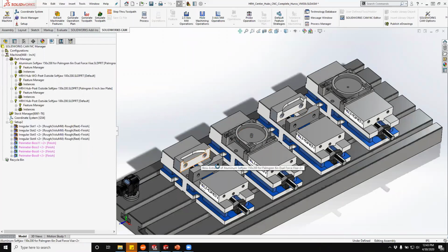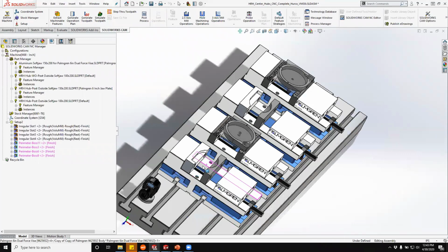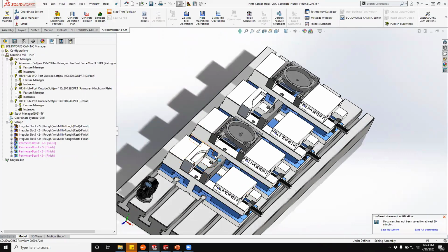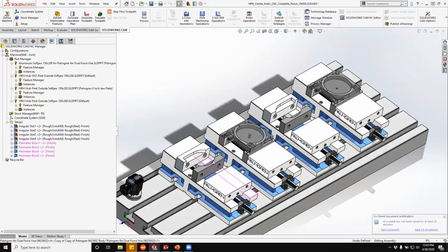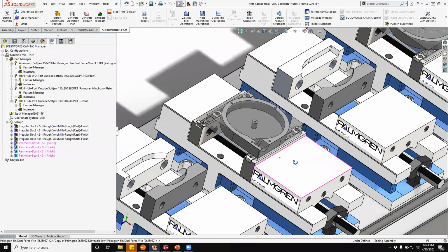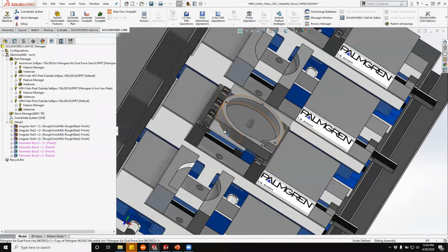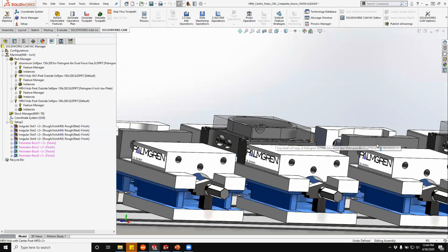I didn't show my 1, 2, 3 block, but I would put a 1, 2, 3 block in between, 2-inch side, close my jaws up, and then I'll cut these shapes out for that flip for the soft jaws. But here you can see we've got our Mighty Bite clamps, and this is our first operation here.